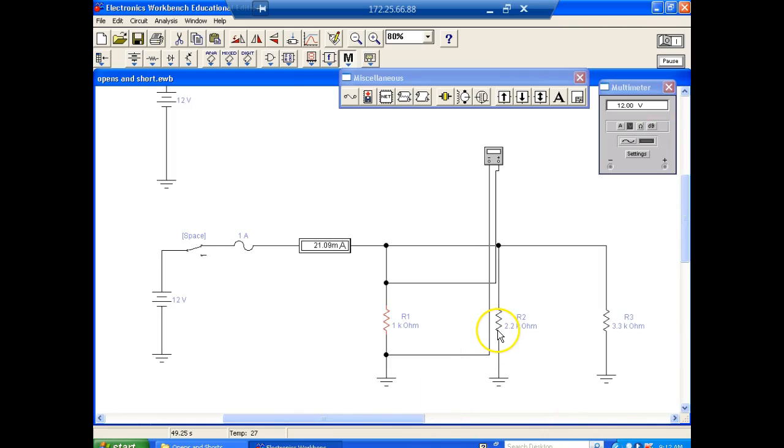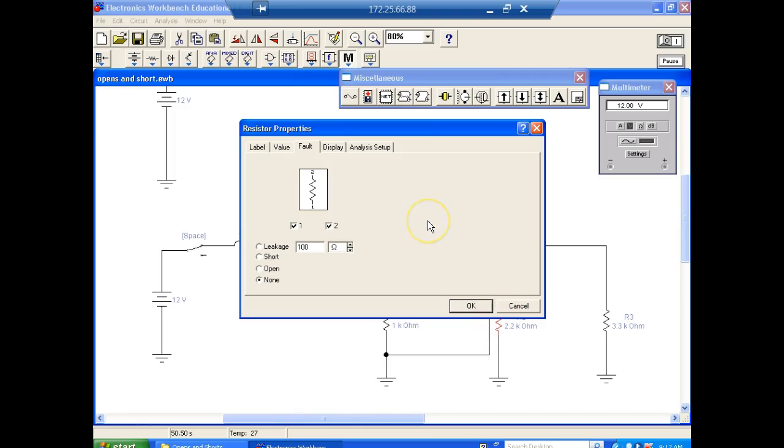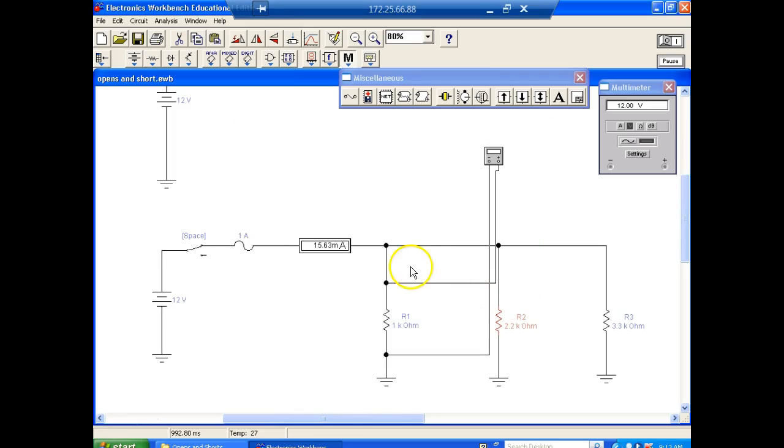Yeah. So if we open this guy, this is an open. This is not an open circuit. This is an open. So notice what happened. Total current went what? Went down, because now we're not supporting this current through here. So this guy right here would conduct the most current because it has the smallest resistance, right? So what happens every time you undo the load, total resistance goes up and total current goes down in a parallel circuit, just opposite of a series circuit. Series circuits and parallel circuits are just opposite of each other.